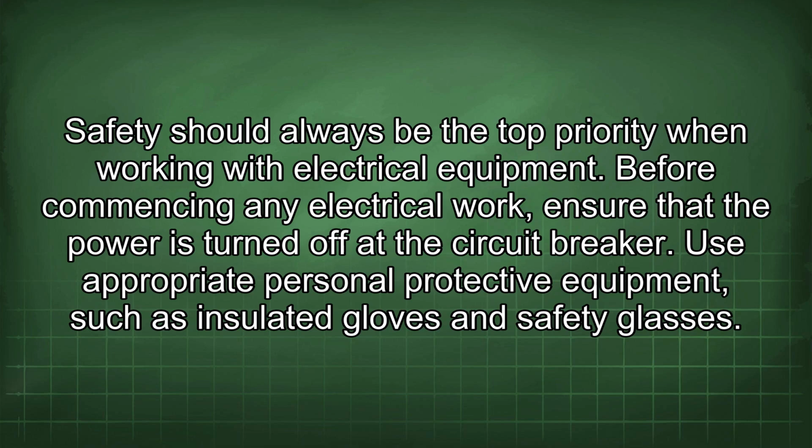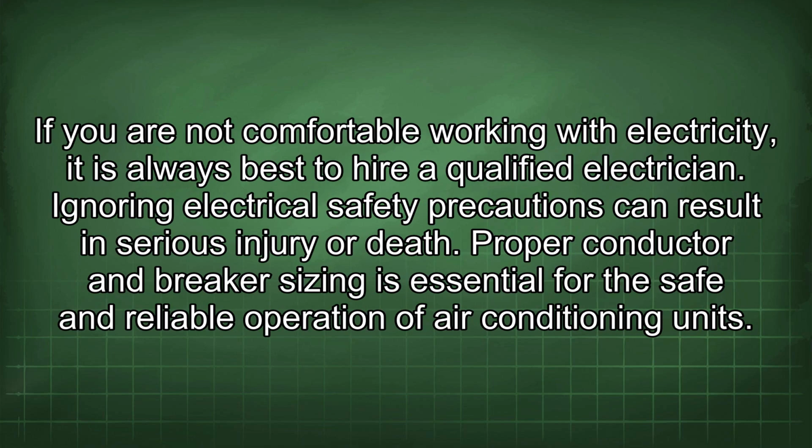Before commencing any electrical work, ensure that the power is turned off at the circuit breaker. Use appropriate personal protective equipment, such as insulated gloves and safety glasses. If you are not comfortable working with electricity, it is always best to hire a qualified electrician. Ignoring electrical safety precautions can result in serious injury or death.